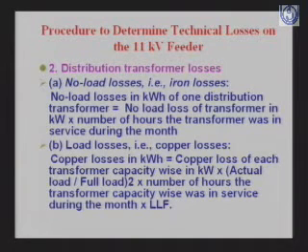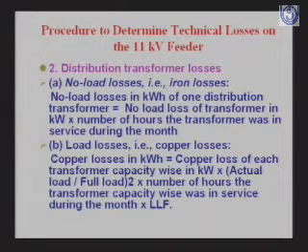I mean, all professional auditors who do energy audit in the industry use this type of method, that is average kVA load divided by the full nameplate capacity of the transformer, square of this multiplied by the full load copper loss. That's the equation which they use while working out the copper losses.